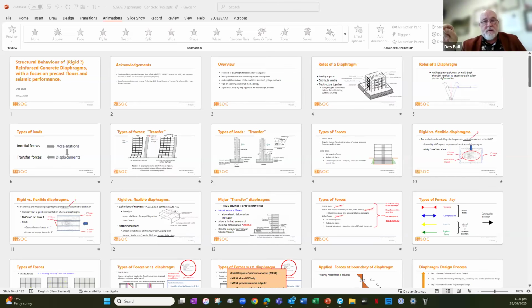So that was my slide referencing that when you've got mesh, ignore it and just go to macros. Use your secondary beams and your primary beams as your picture frame for your strut and tie, and ignore the mesh. To be honest, that's where we are now, and I stand by that. I was literally thinking about that this morning. There might be one or two cases, but they're extremely rare. I knew this question would come. So it's a general rule. The answer is we don't, and it's in the yellow C5, we don't rely on the mesh in these systems.